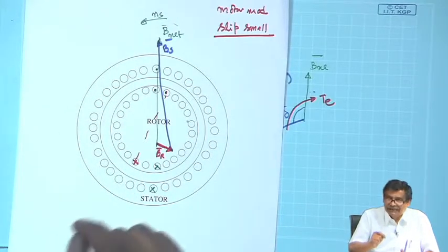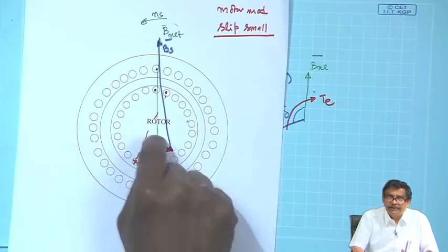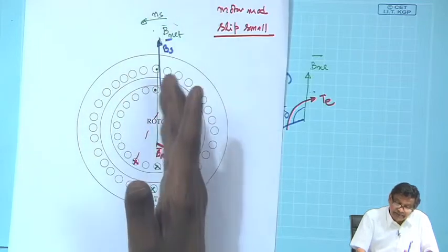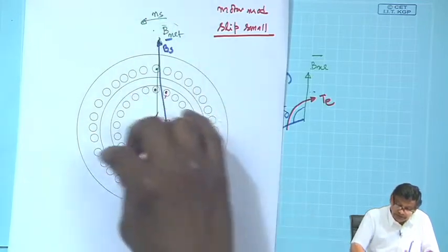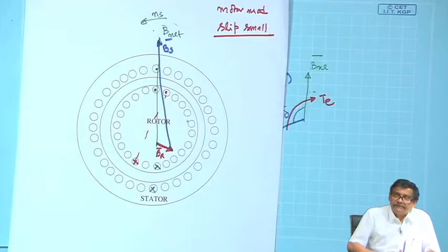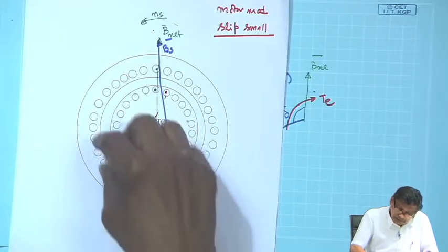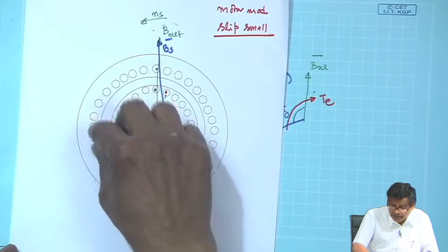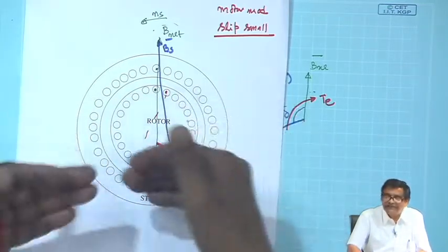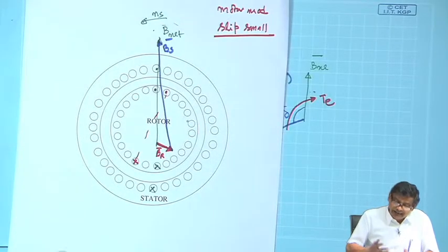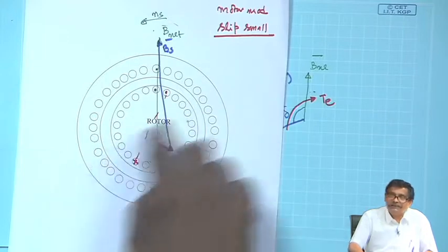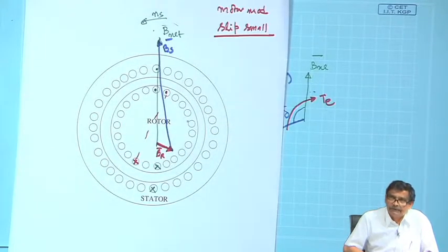That is the information I have used here. When I say that Bs is here, I mean that perpendicular to this line, whatever phase exists here, they are carrying maximum current, or whatever phase belts A or B phase, their together effect is that one. So, I can say if this is Bs, perhaps A phase maximum is here, something like that.